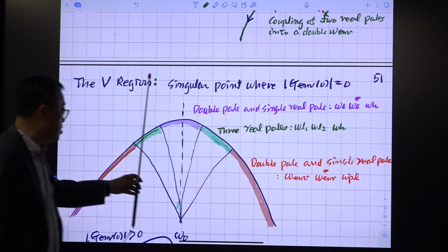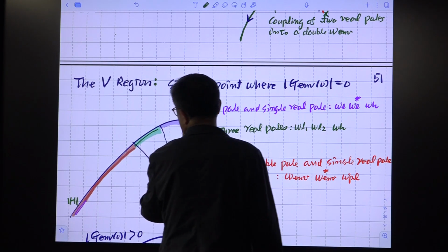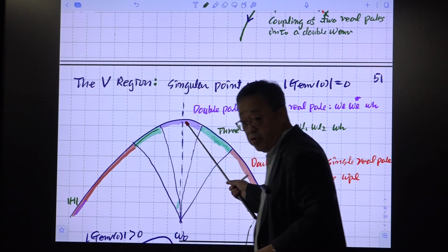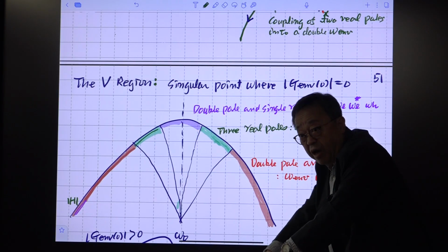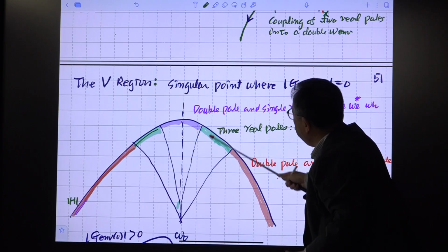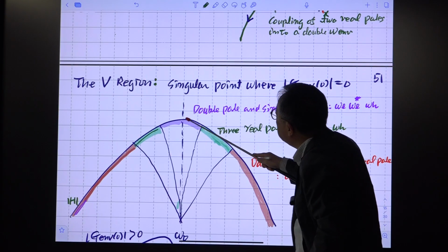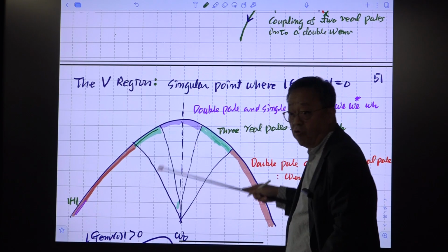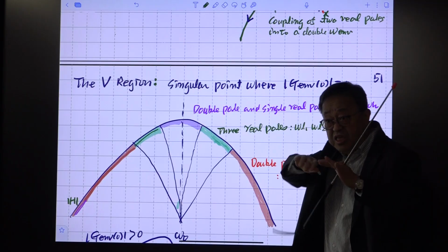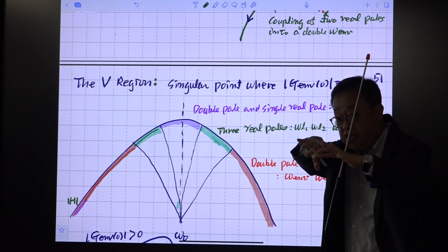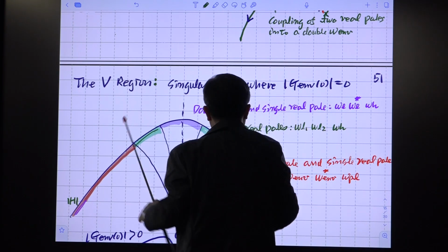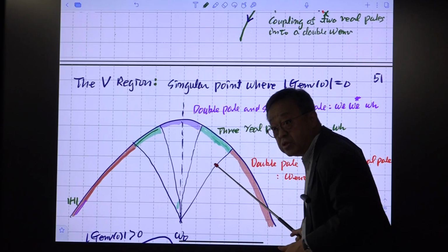At this point, if the switching frequency is at the resonant frequency, the magnitude becomes 0. And if the switching frequency is near this resonant frequency, you have a double pole at low frequency. If you increase the distance between your switching frequency and the resonance in either direction, you have 3 poles.